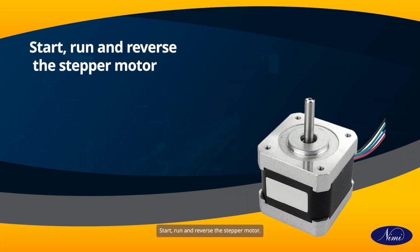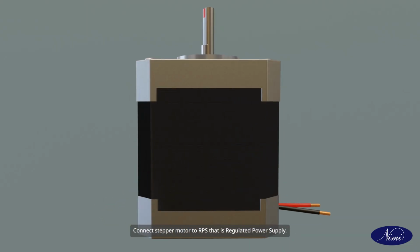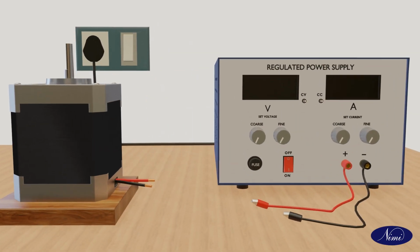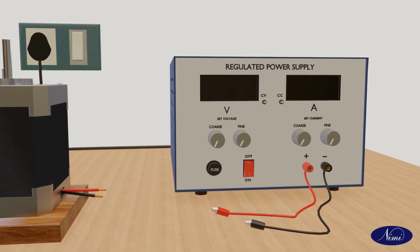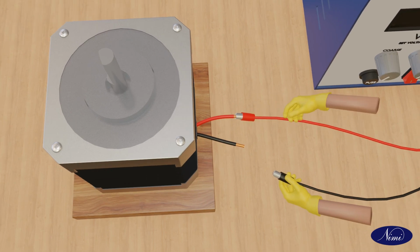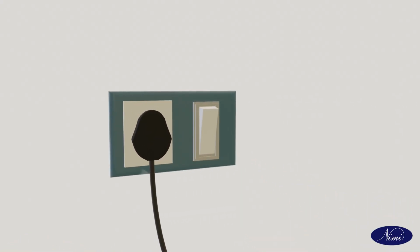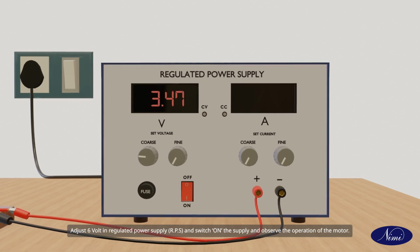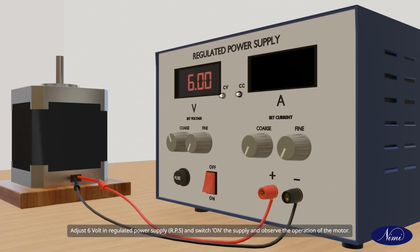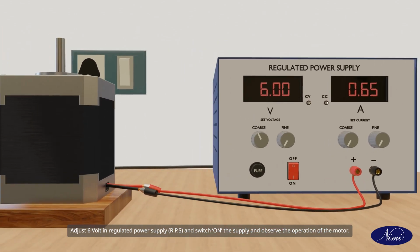Start, run and reverse the stepper motor. Connect stepper motor to RPS, that is regulated power supply. Adjust 6 volt in regulated power supply and switch on the supply and observe the operation of the motor.